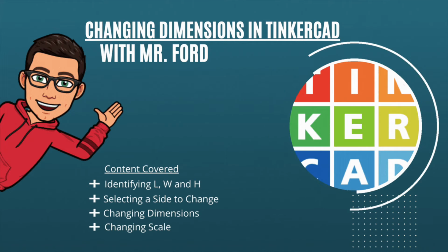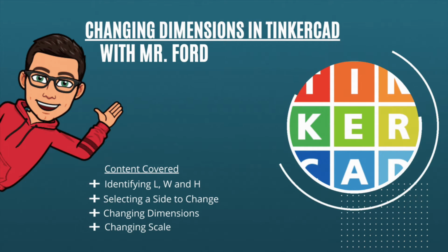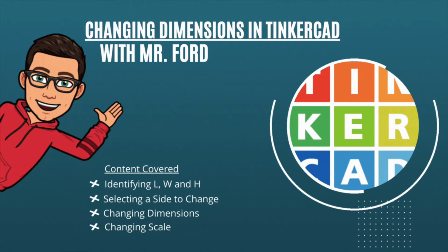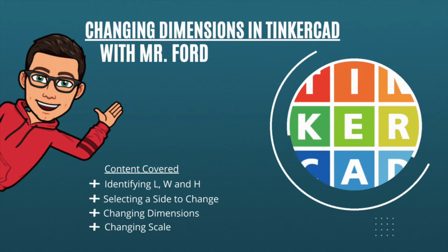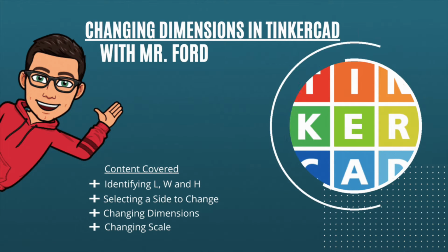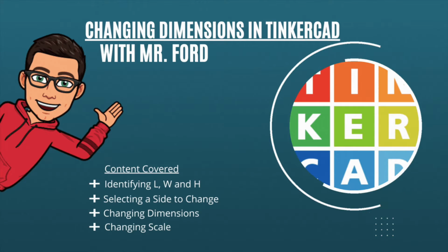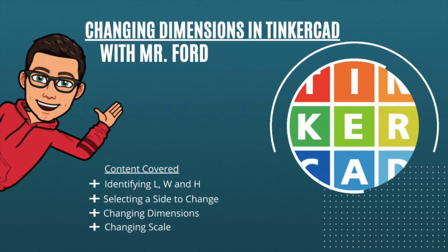Hi, Mr. Ford here, and today we're going to be taking a look at changing dimensions of a shape in TinkerCad. Content covered in this video includes identifying the length, width, and height of a shape, selecting a side to change, changing the dimensions, and changing the scale of your overall project.